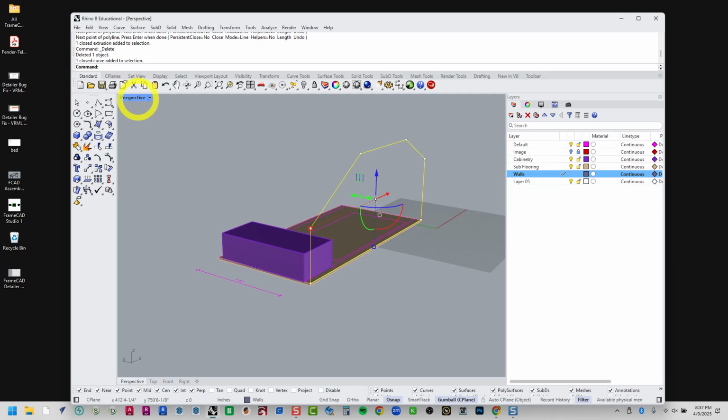Right? If you've ever had that situation happen to you, where you get something like that, but in this view it looks perfectly fine, right? You're like, huh, why does it look so perfect here? And then I come to perspective view and it's looking like that. The reason why that happens is because sometimes when you're snapping to certain objects or not snapping to certain objects, you don't realize it, but you're snapping to something that's really far away in your 3D model.